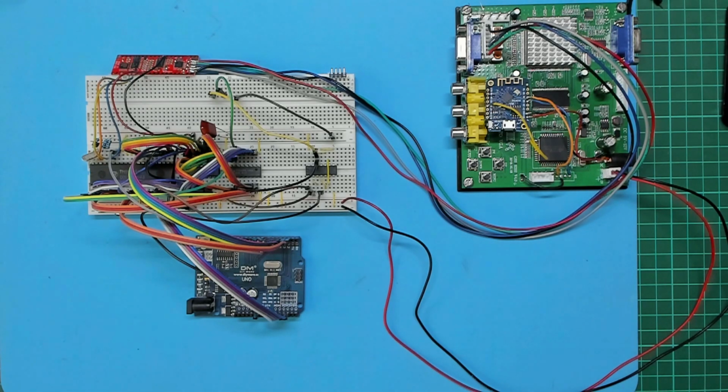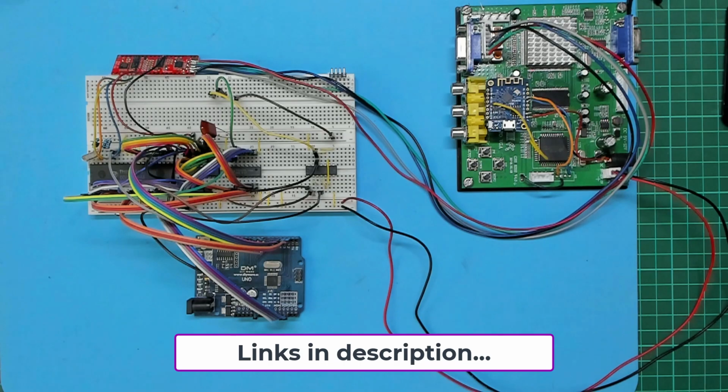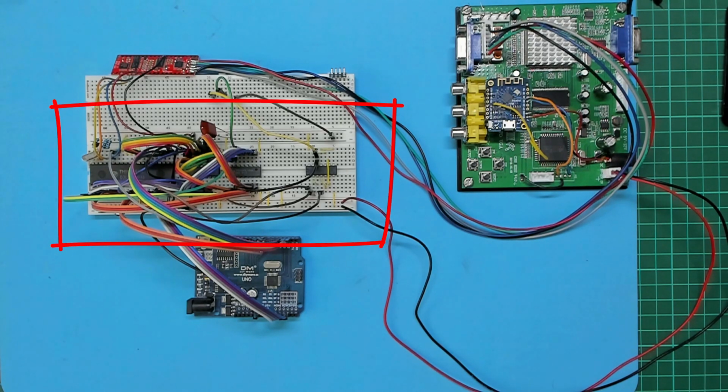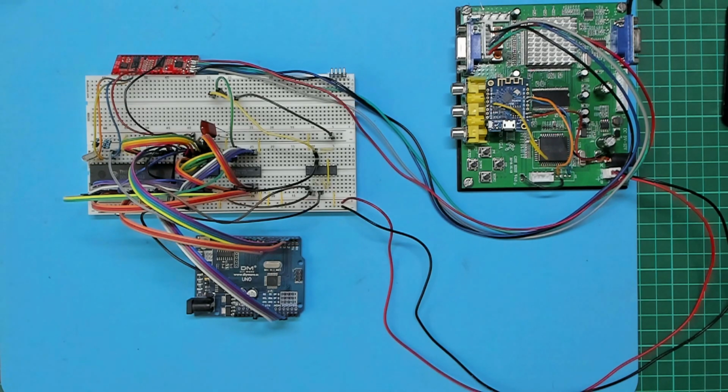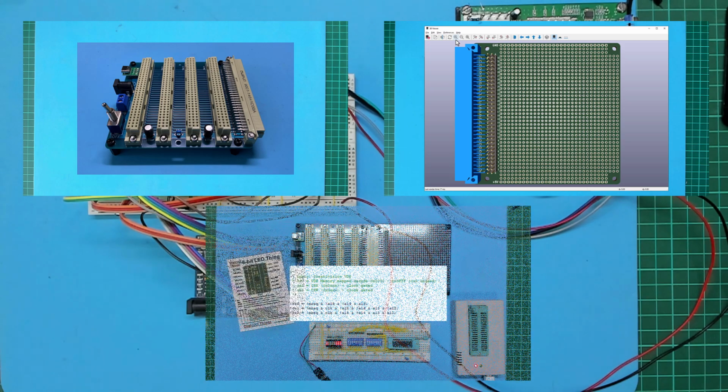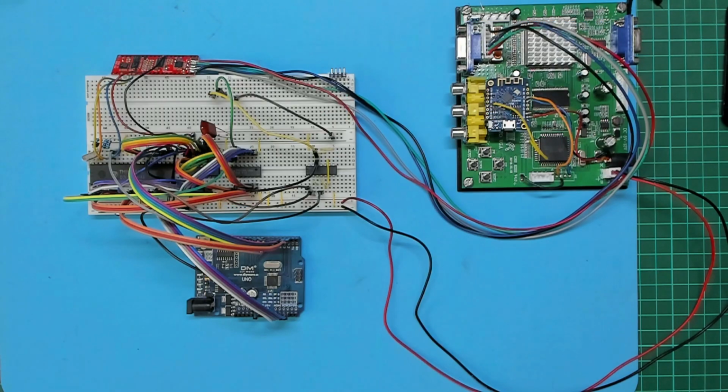Earlier I posted an article and video on my TMS9929A Video Display Processor (VDP) Rediscovery. This included designing an alternate Retro VRAM solution, which I then implemented as a breadboard prototype and also verified successful operation. Having built an MECB Backplane and my first actual MECB card, a prototype card, and also having proved the PLD-based address decoding logic, now seems like a good time to implement my TMS9929A-based VDP circuit design onto a PCB as my first MECB video card.